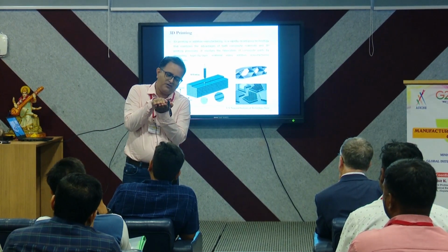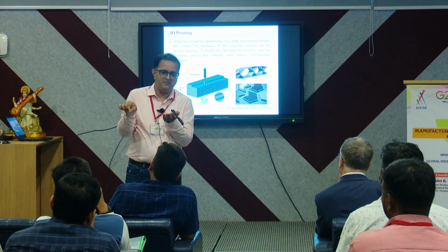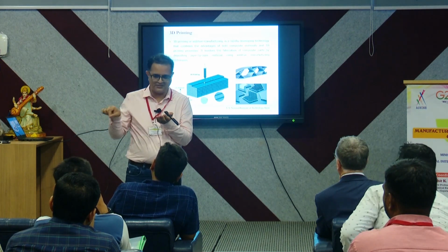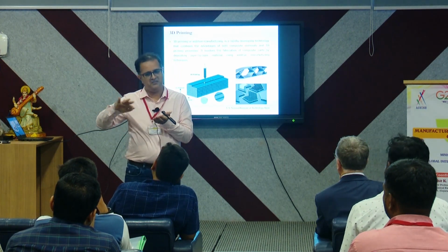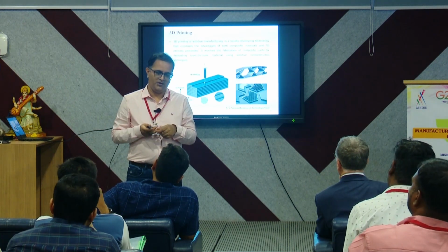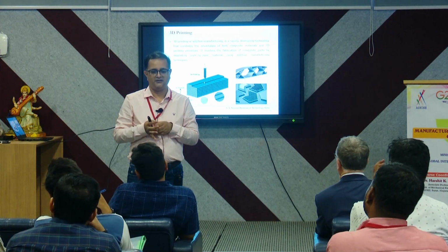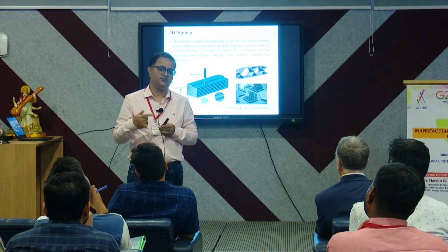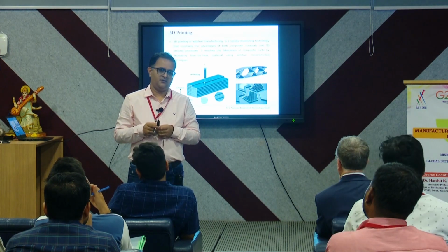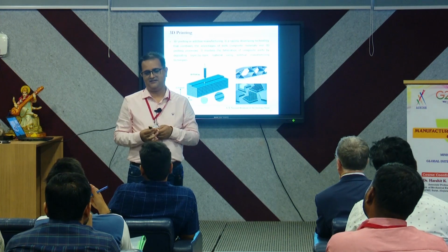A crease that comes over the other becomes a porous part. Often the resin does not pass through it well, and you see that it is solidified, but often there is air entrapped in it. So in spite of all the care that you take, those inherent problems that you face with the fabric remain. But when you are pulling out air, there is no possibility that there is air inside.